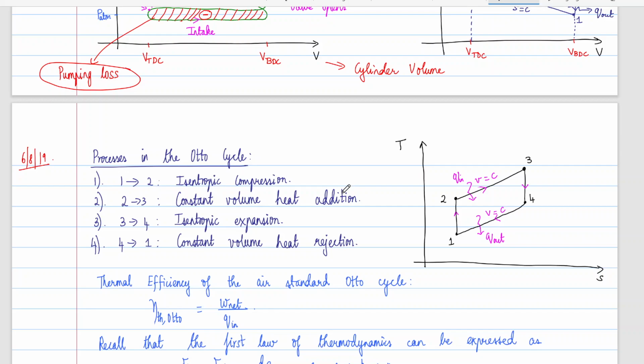If a clutch is there, can I mount it on two independent shafts directly through a keyway kind of thing? Yeah, you can add a clutch between two shafts, assuming they are in line, right? If you want it to be RPM specific, like below a certain RPM I don't want my motor to move, after a certain RPM I want it to move, then that is what the clutches in our scooters do, right?